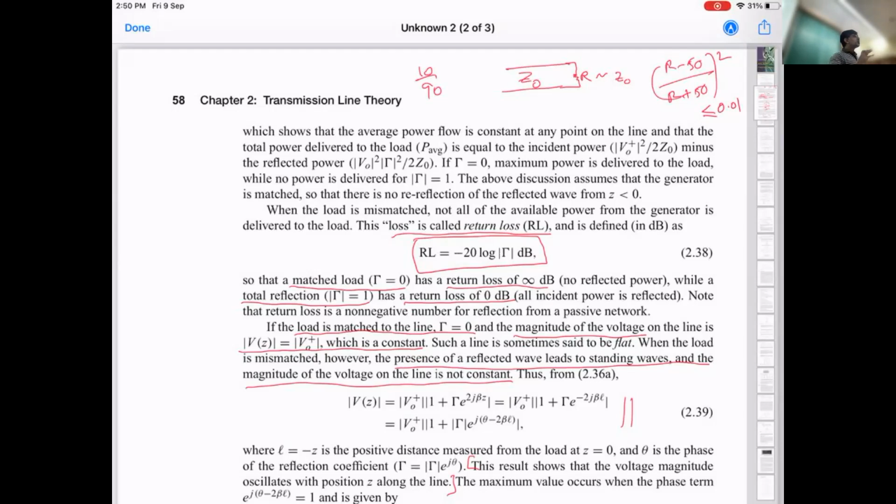Now, if you compare these two pictures, it's only 1% reflected power versus plus or minus 10 ohms of variation on 50 ohms, they look very different in terms of how much change we are talking about, right? 1% sounds like a very small number, but 10 ohms on 50 ohms is a 20% variation. This is connected to things which will come later, but this is the point I was talking about, that the figure of merit really depends on what you're trying to do. From the perspective of power delivery, this is absolutely fine. It's 99% power, I'm happy with it. In some cases, even that is not very good.